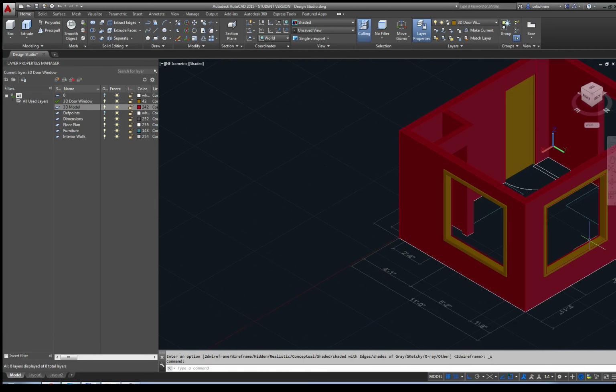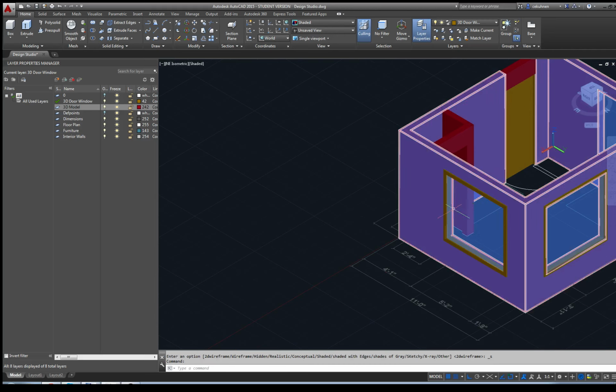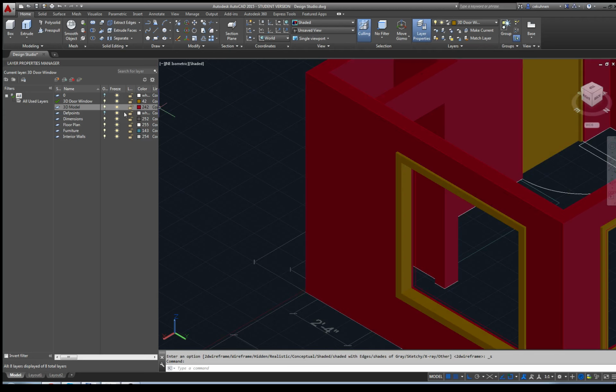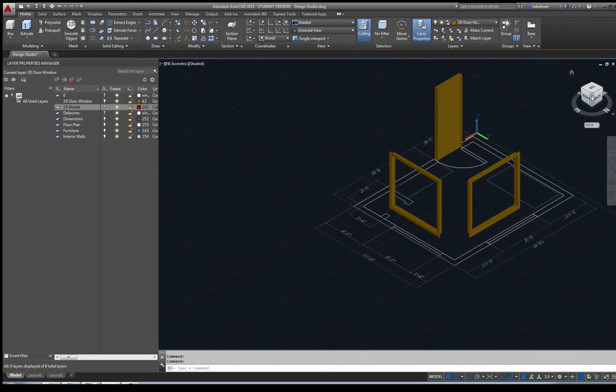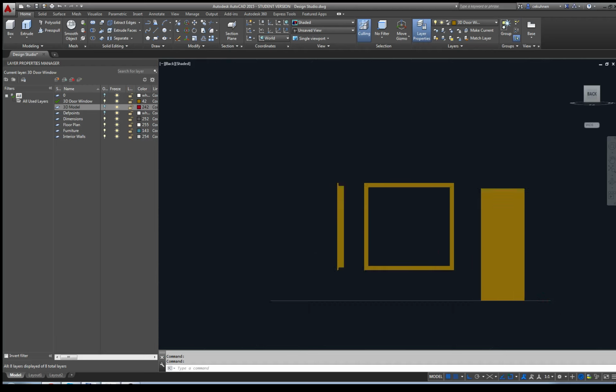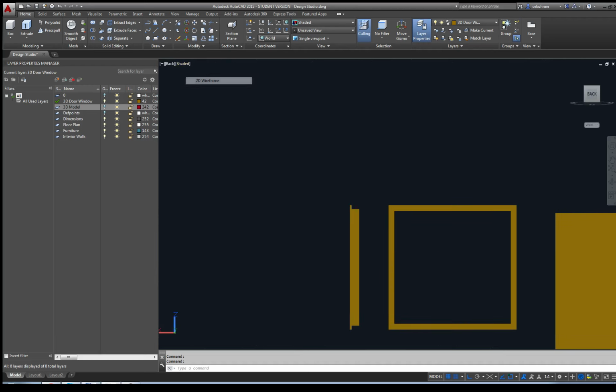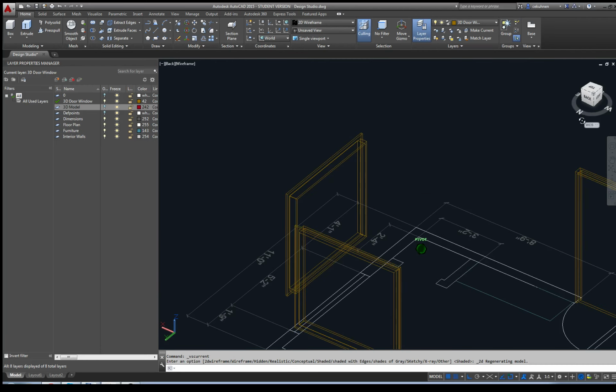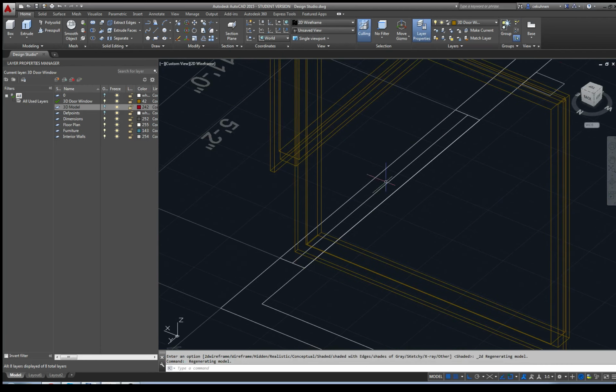Now let's say I would like to have a window with 2 windows, kind of like with a plus inside, so I would have to do a little bit of measurement and math. So I'm going to turn off my walls for a moment, because that's going to be easier. Let's turn this to a wireframe mode. Let's go maybe to this view.